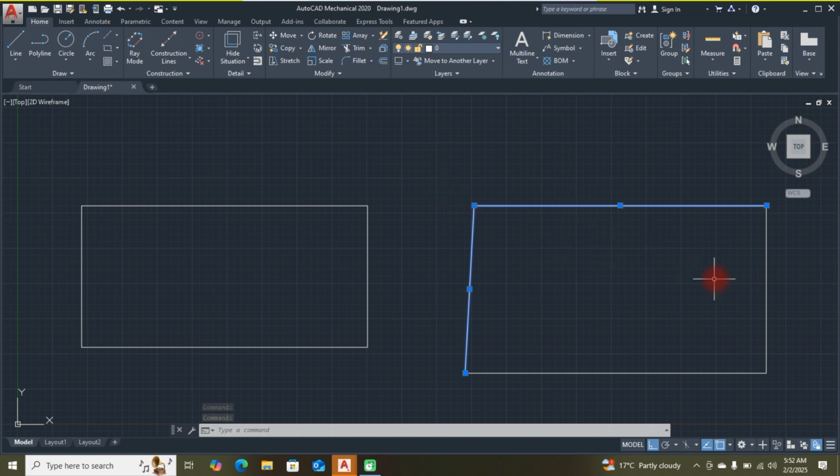I want it to form a complete rectangle. That is, if I highlight like this, it is completely joined. So to make it completely joined, I just have to select like this. Then you can find a joining command on version 2024 here on Modify, where you'll be able to see Join. But even for that one, you just type join. Before you even finish, the command is there like that. So as you can see now, the figure is joined.